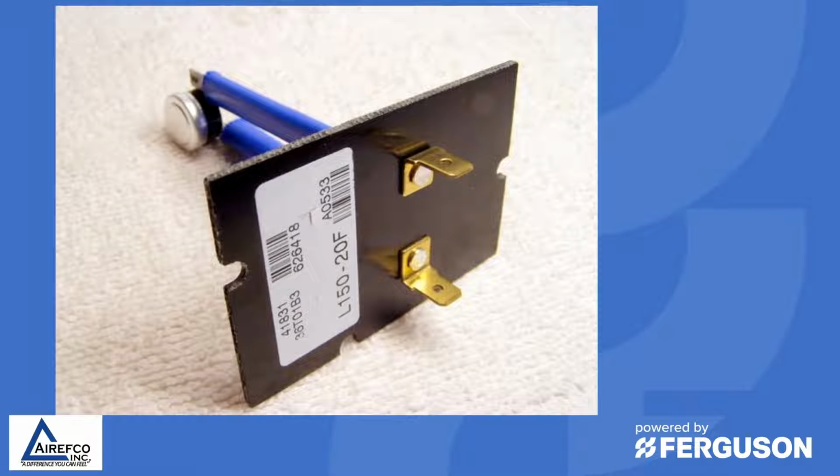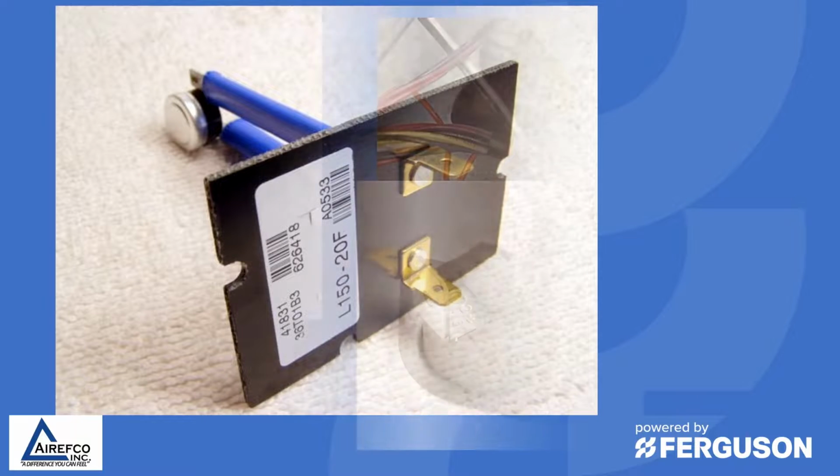This is another design of high limit switch with a little click-on switch that is inserted in the heat exchanger compartment. And this particular one is designed to trip at 150 degrees. Some of these switches have the limits printed directly on them. Others you would have to call a parts department to get the specifications for that limit switch.